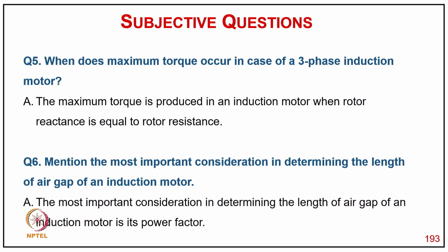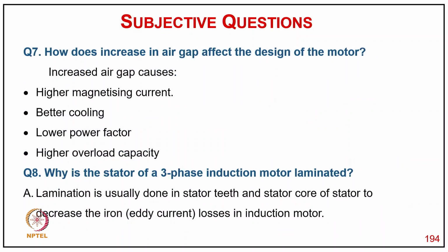The most important consideration is determining the length of the air gap in the induction motor. How does increasing the air gap affect the motor? Increasing the air gap causes higher magnetizing current, a lower power factor and higher overload capacity.